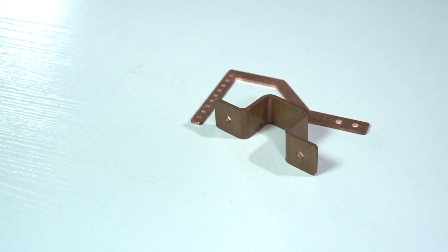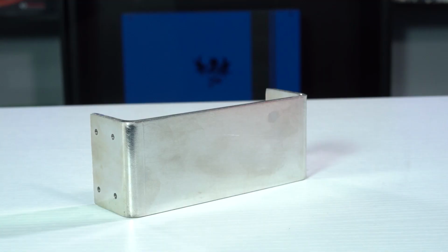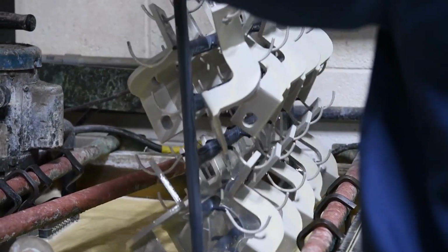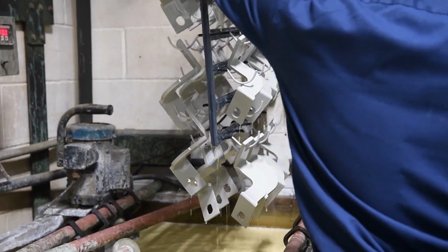Before we finish off, I just wanted to touch on copper bus bars, which we also make here at Protocase. Copper bus bars are typically put into a custom enclosure or a board so that it distributes a significant amount of current. Copper bus bars can be part of a fully custom enclosure design or a standalone part. We also offer tin plating, which will improve the corrosion resistance, electrical conductivity, and solderability for copper bus bars. Similar to anodizing, tin plating is completed through a third-party supplier for additional lead time and cost.